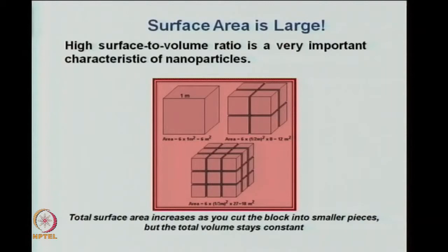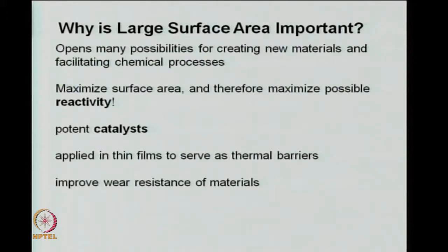If you take a large cube and cut it into several small cubes, the surface area will increase, and hence for the given volume you have much larger surface, which is characteristic of nanoparticles, and hence enhances any property which depends on the surface like reactivity or catalysis, etc. So, the surface area is a very important property for catalysts and for increasing the reactivity, and there are many other applications in thin films where you use certain nanomaterials to act as thermal barriers to prevent something from getting too much heated, or the wear resistance of materials which are being used rapidly, and this wear resistance of materials can be enhanced by decreasing the size of the particles on the surface.